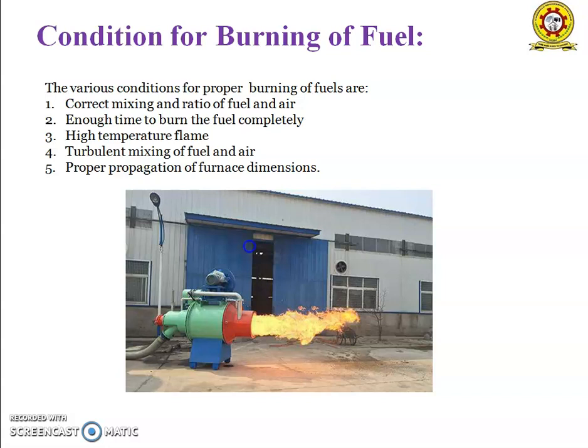A pulverized coal burner should satisfy the following requirements. It should mix the coal and primary air thoroughly and should bring the mixture, before it delivers to the furnace, in contact with additional air known as secondary air to create sufficient turbulence.